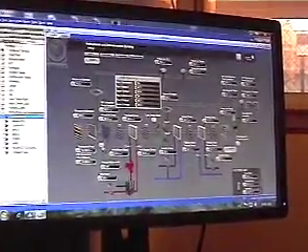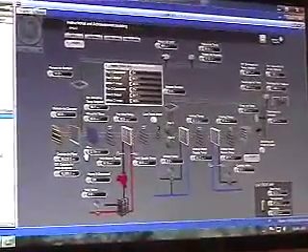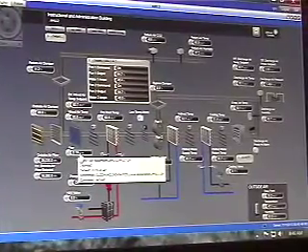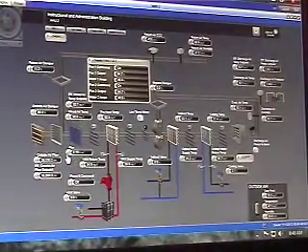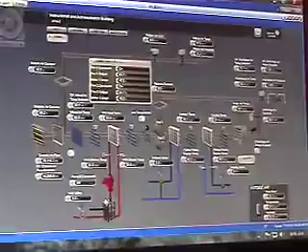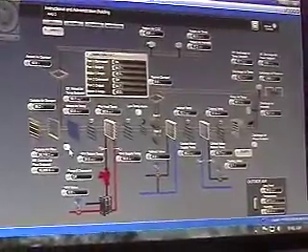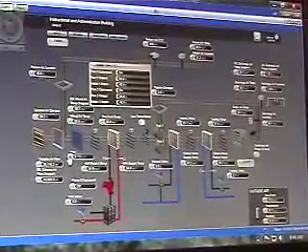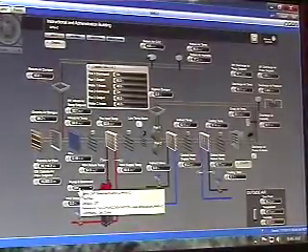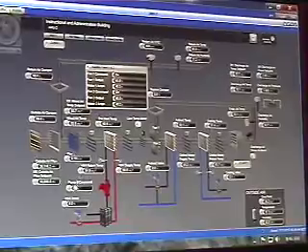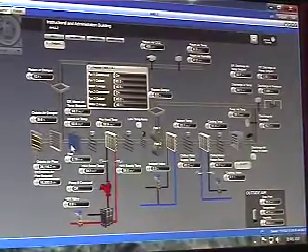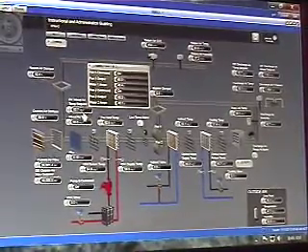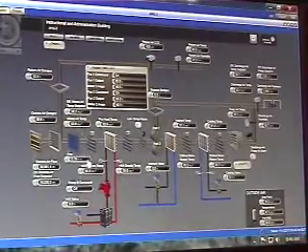This one right here is set to a switch. It's set to an alarm, but it also actually reads the filter differential pressure. This is one that he's collapsed, so when you first look at it, it's just collapsed. If it goes into an alarm, it'll turn red. Otherwise, if you wanted to expand it, you can look at it and see what your actual pressure drop across the filter is. Going through, you have your mixed air temperature and your set point right here.